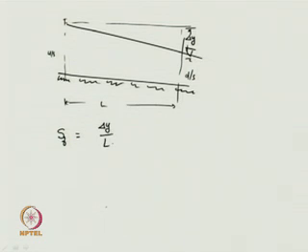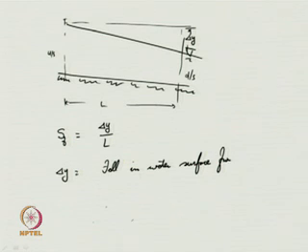That is not theoretically correct, but that is the initial approximation. We are suggesting that the component of velocity head in this case is very negligible in determining the energy slope. So, therefore, the energy slope SF is given by del y by L, where del y is equal to the fall in water surface from upstream to downstream in the reach.